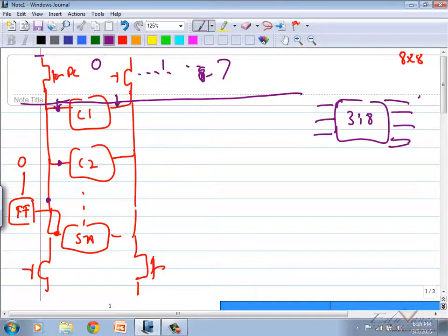Following, yes or no? Look here, how big this transistor is will govern how fast these nodes will go up to VDD. Until all nodes go up to VDD, can you confidently say that this node is at VDD? No. Understood? Inversely, you have to size these guys also, so that they can pull it down to ground faster. So what are the sizing constraints? Precharge and your pull down circuitry as well. Write enable, sense enable, all of that. Understood?